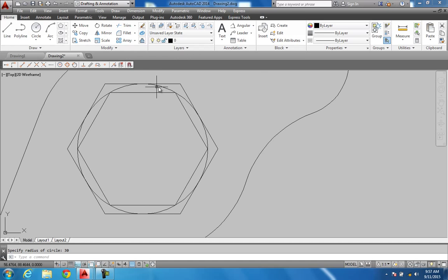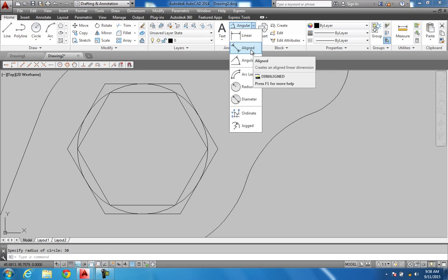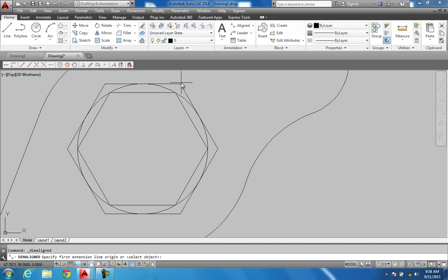And what that means, if you're trying to figure this out to make it in more simpler terms, is when you do a circumference, you'll be measuring from flat to flat. If you are doing inscribed, it'll read from point to point. Okay? So that's the difference between those two.